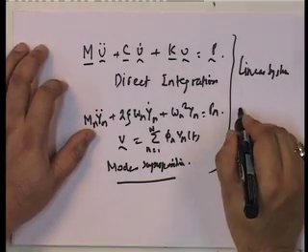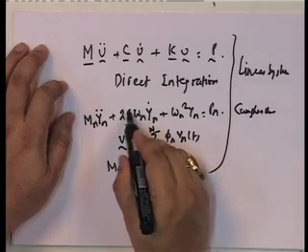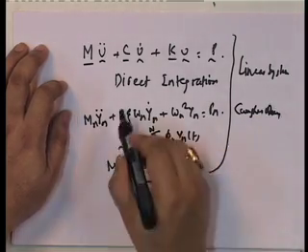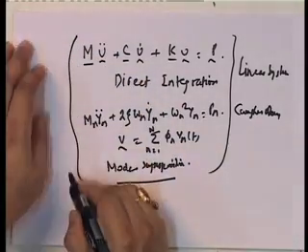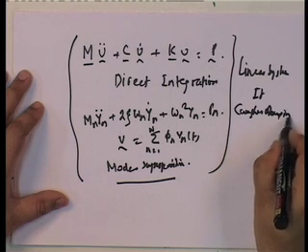If we use Caughey damping, where we enforce that xi is the same in every mode, these two methods will give the same result.